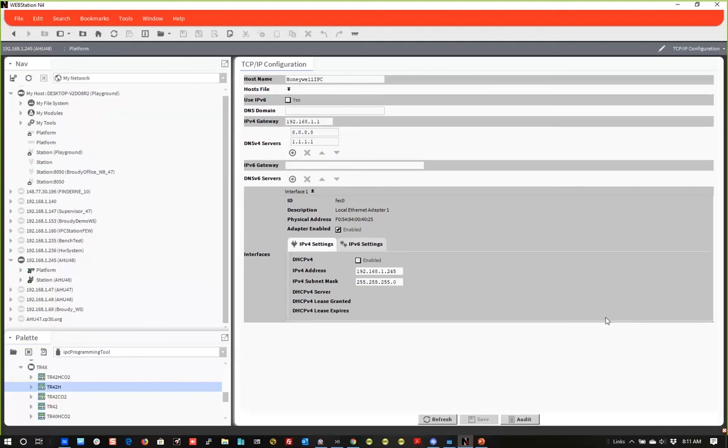It's the IRM controller, or it's also been called the Spyder 5. They're looking at a VAV version of that as well, to be a competitive model if somebody wants to stay in the MSTP world for VAV control. So yes, there should be a couple VAV options coming in the future as well.